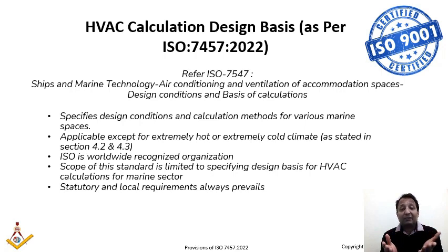As the name suggests, the standard ISO 7547 is Ships and marine technology, air conditioning and ventilation of accommodation spaces, design conditions and basis of calculation. Here you need to remember that this standard is applicable to ships, and it is not applicable to the offshore structure, the oil and gas structure. That is a separate standard which we are going to check in subsequent modules.